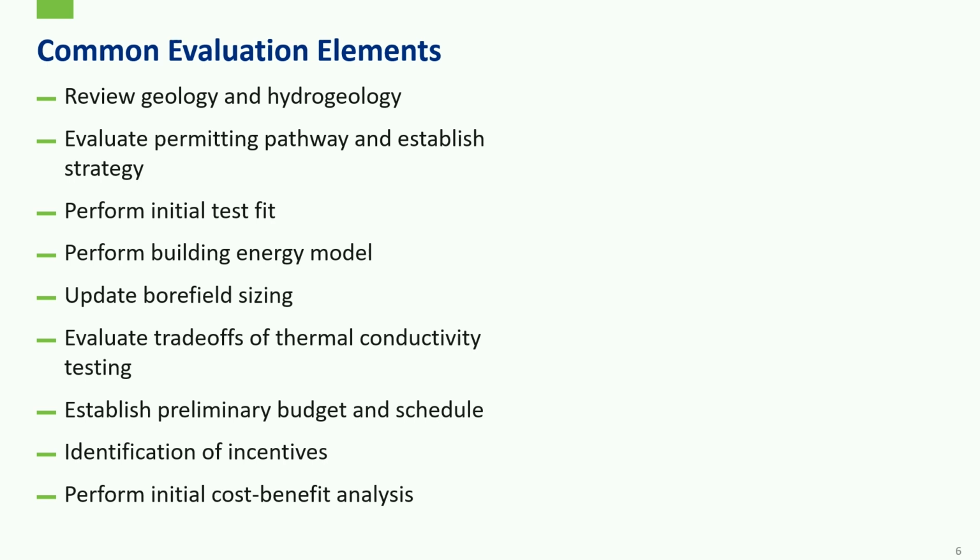So anyway, a couple of these models get developed, but when you're designing the bore field itself, you want to have your own building energy model so that you're either as aggressive or as conservative as your company really wants you to be. And then you're sizing that bore field on the basis of what your model is and whatever guarantees you might have to put up thereafter.